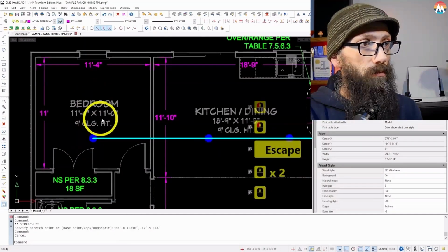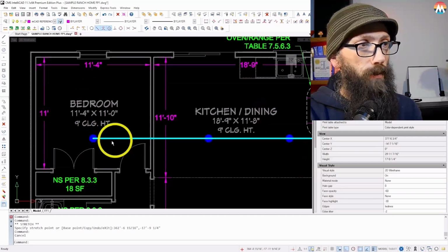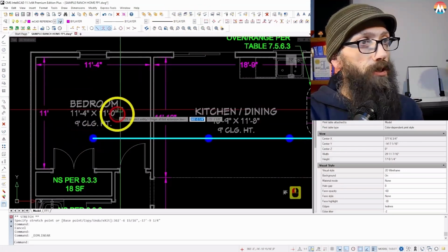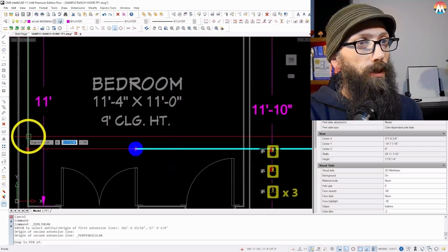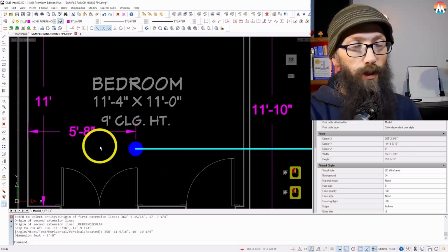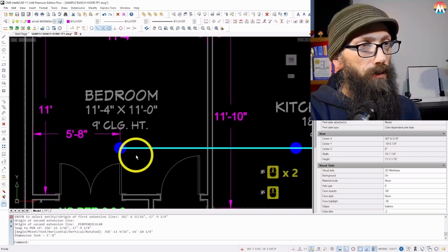Now, if I want to minimize pipe and stuff, I could max out the 8 feet off of this wall as well and bring this over here. There's just so many ways to do this. Let me show you another way. I think I've shown you like 2 so far. So that's 5'8". We want to go to 8 feet, so that would be 2'4".